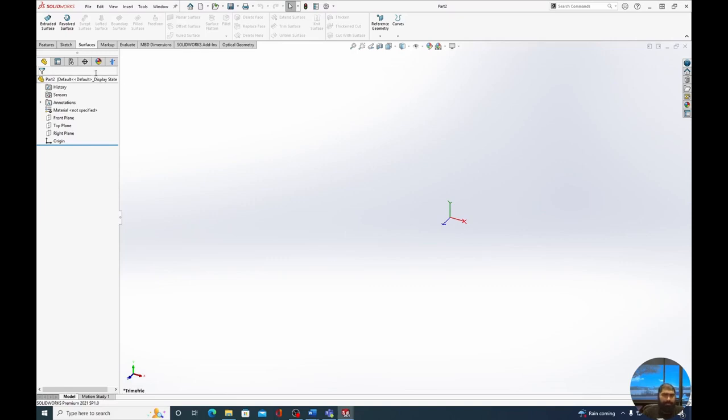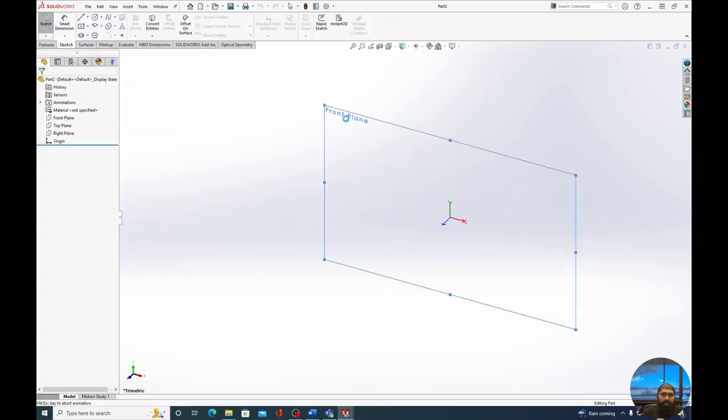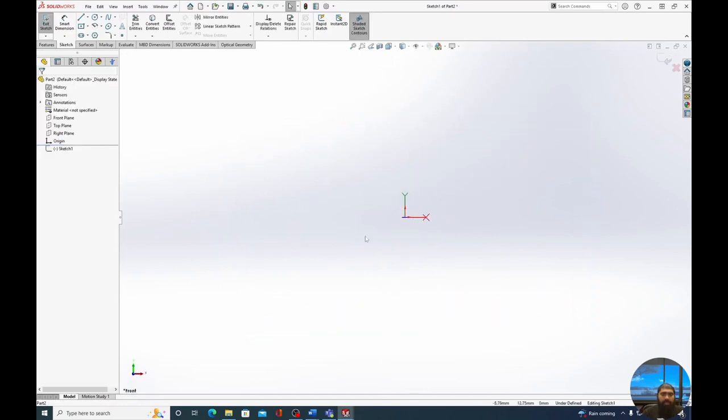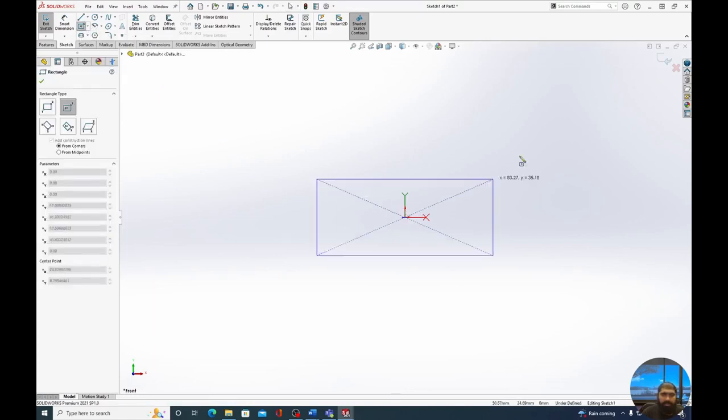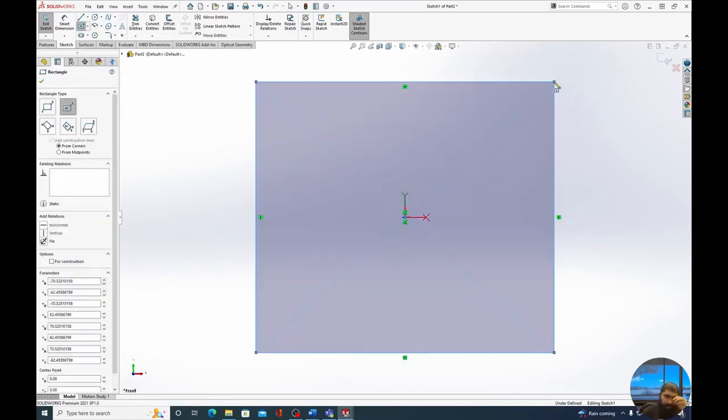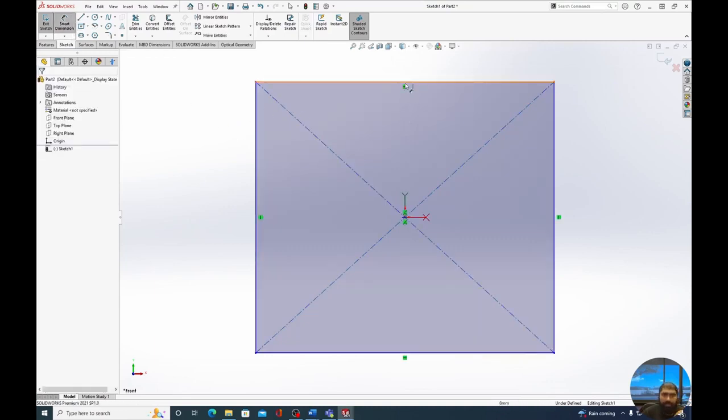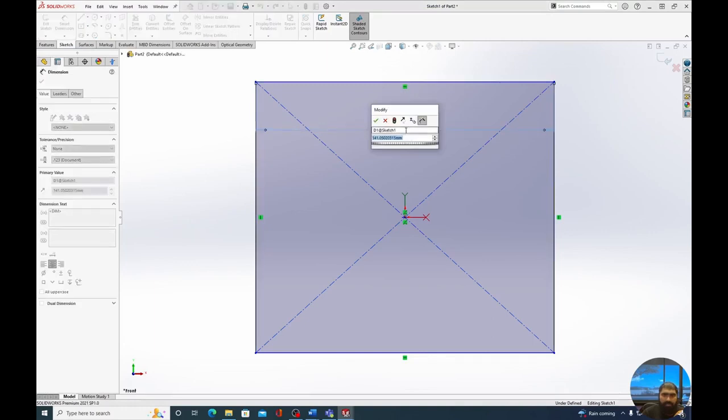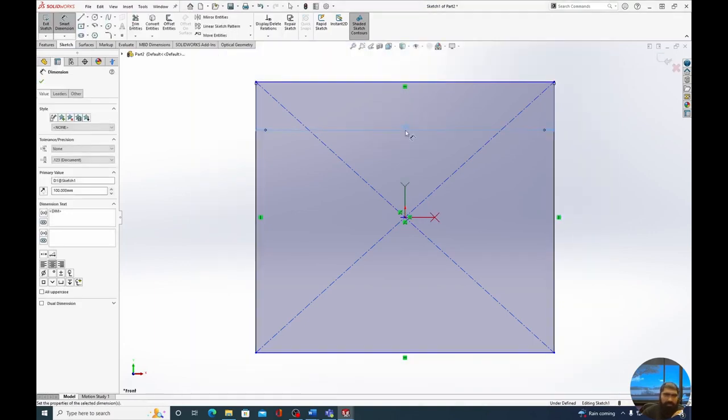And you'll remember in our previous model, we decided to have our parabola propagating in the Z direction. Now we will go to sketch and select the sketch command, and this time we will do the front plane because we want our target to be along the z-axis, parallel to the xy plane. So we will select the center rectangle, go to the center, extend it out this way, and now we will select the dimensions. So we go to Smart Dimensions, top one, let's set it to 100, press enter.